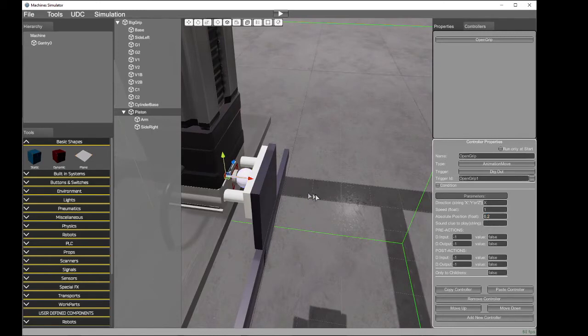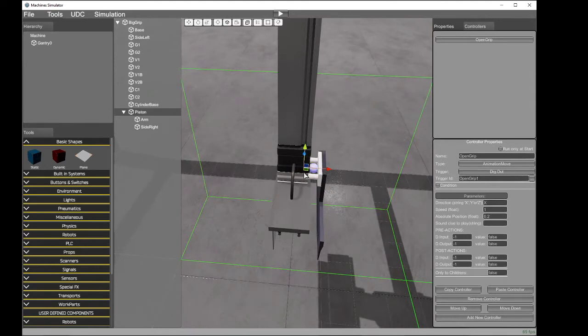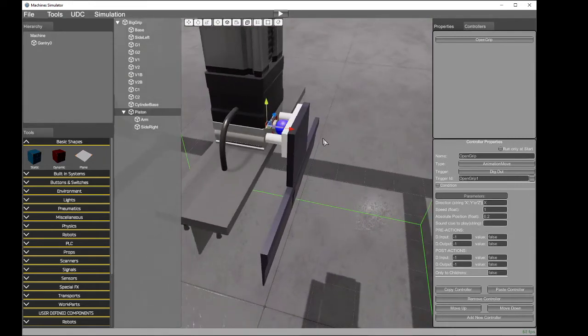0.2, because the amount to move the piston is a small quantity. We can add in a soundtrack each time this movement is executed, and this area is important. Pre-action and post-action: we can program an action to do just before and just after moving the component. In this case, we must activate a digital input to inform that the movement has been done. Then here we must write the PLC input we have defined in the user defined component, and the value will